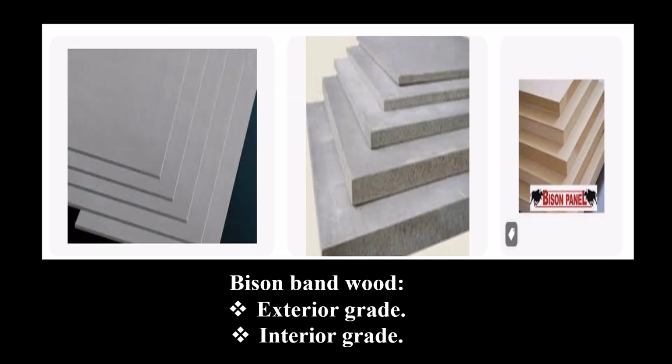Bison board, exterior grade and interior grade. Exterior grade bison boards are treated with chemical so that it can resist climatic effect of temperature, wind and other effects. Interior grades are not treated with chemical because they are within the building which are not affected by climatic effect.